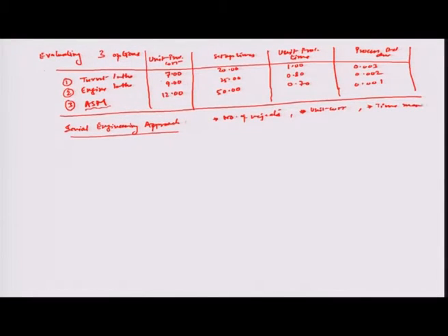These were recorded for the pieces which were supposed to be produced, namely about 1000 pieces, and we found that with a mean of 1 inch diameter and a process standard deviation of 0.003 inches, that is given for the turret lathe, the unit cost of the product happened to be about 23.97 currency units, in this case US dollars, for the turret lathe alone.